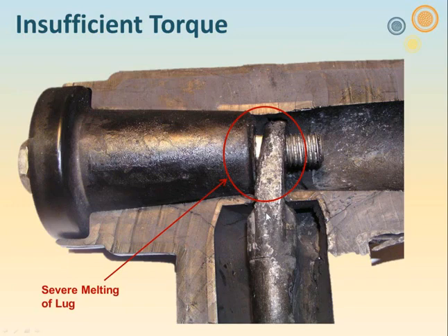Now, when you first look at this picture, I'm sure the first thing everybody keyed on was the fact that we are looking at 1/3 of this lug and we don't see any crimps, which means the first crimp is way down. Even if they started down here and all the crimps were put on right next to each other, there's no way that they would be able to get the proper number on.